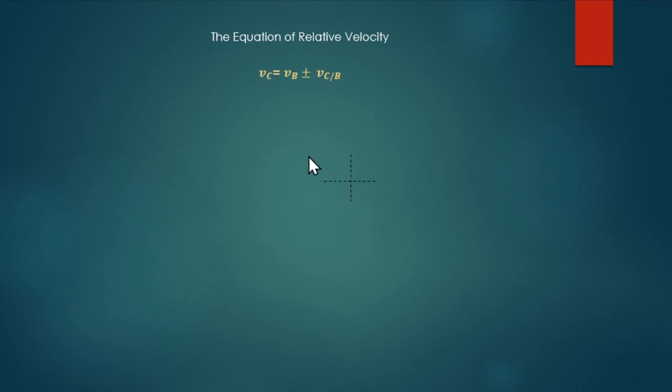So at Q, we have this 20 millimeter. So the magnitude of your velocity B at the tip is equivalent to 20 centimeter per second, or on your graphing paper is 20 millimeter, and measured at 30 degrees along with the negative x-axis.